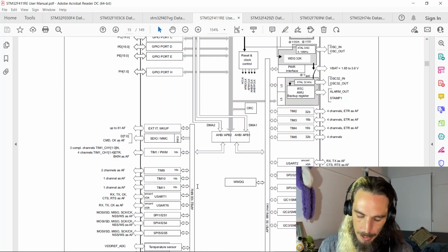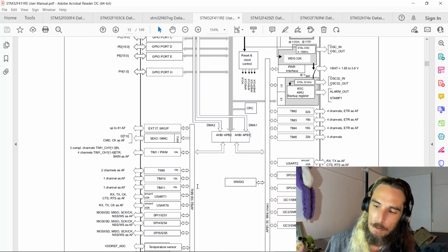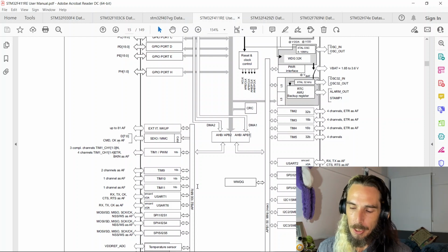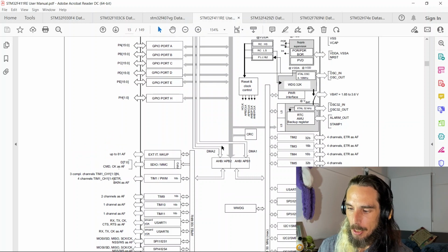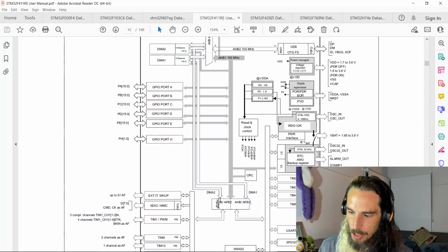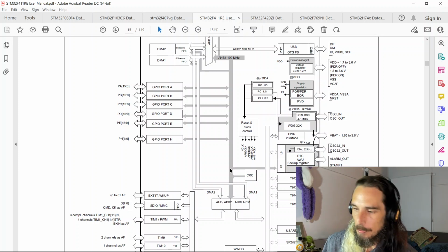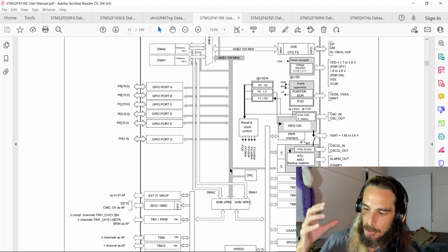So the APBs are advanced peripheral buses, and it's another type of bus that ARM has developed, which allows peripherals and things to be connected. It's less advanced than the AHB, typically 32 bits wide, so it can't fit as much data per clock cycle, but it's perfect for being able to connect a bunch of various devices. And the bridges here that I mentioned basically allow the translation of signals from the AHB to the APBs.